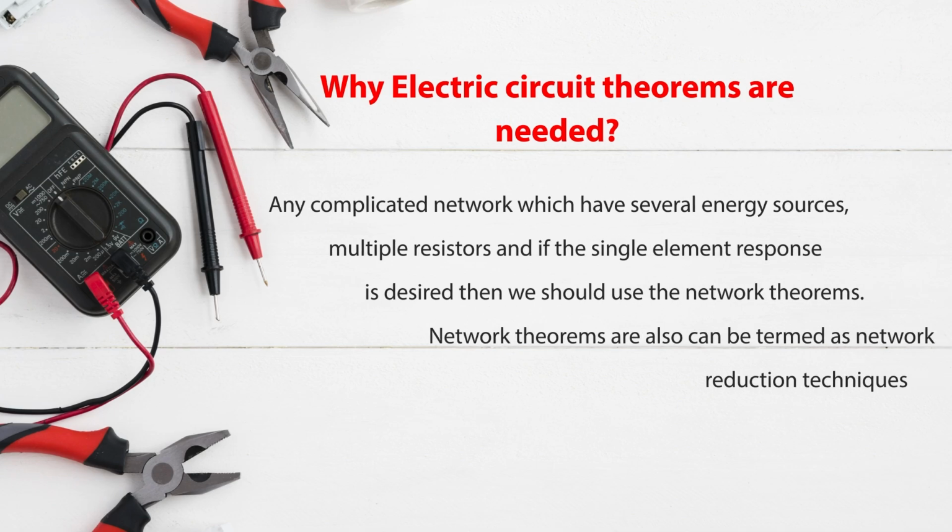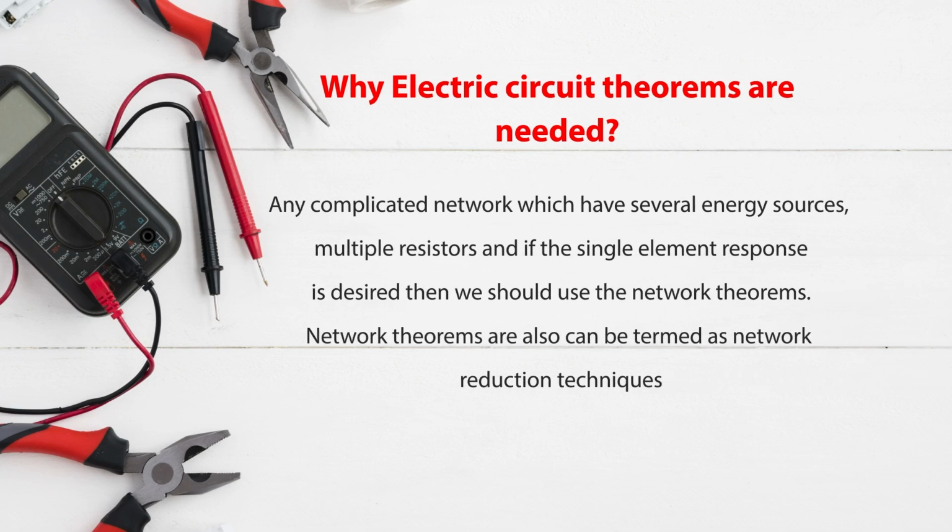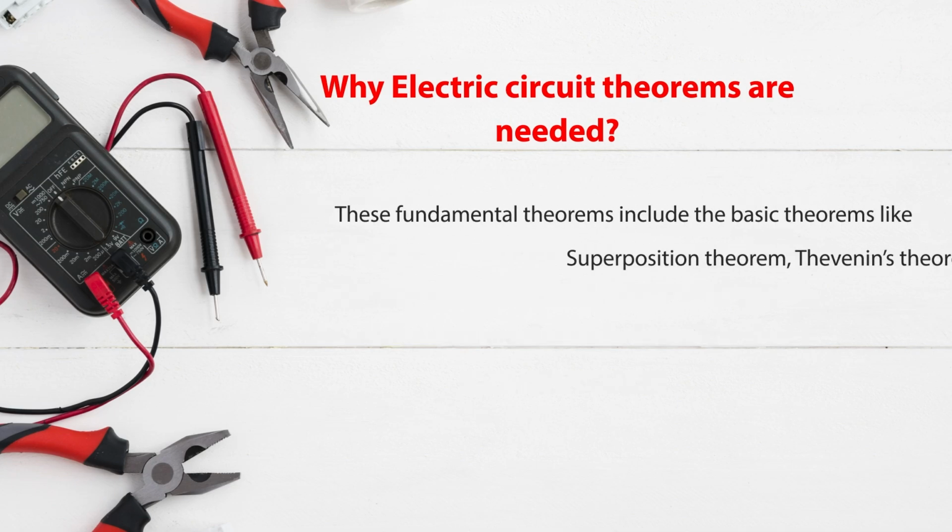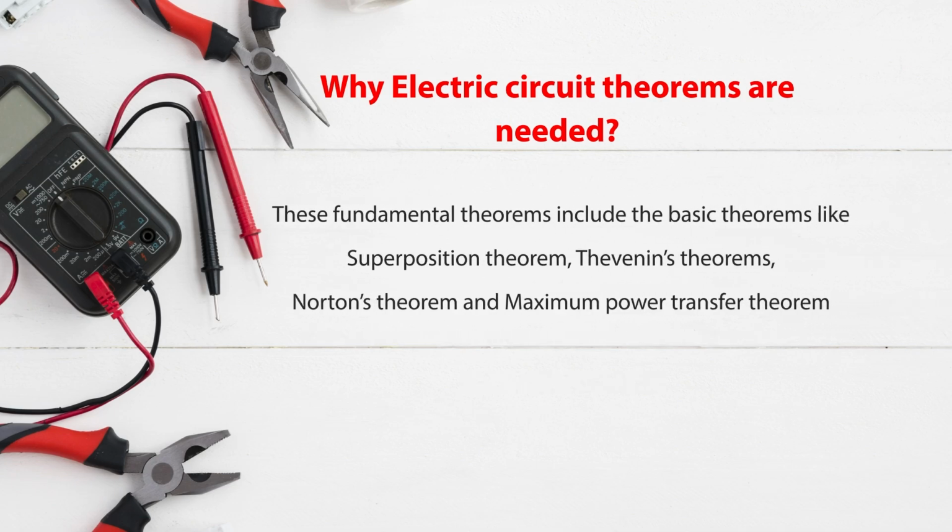For any complicated network which has several energy sources, which may be voltage sources or current sources, and also multiple resistors, if a single element response is desired, then we should use the network theorems. Network theorems can also be termed network reduction techniques. These fundamental theorems include the superposition theorem, Thevenin's theorem, Norton's theorem and the maximum power transfer theorem.